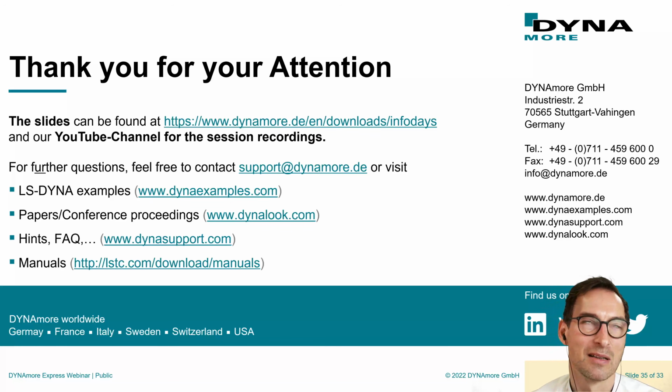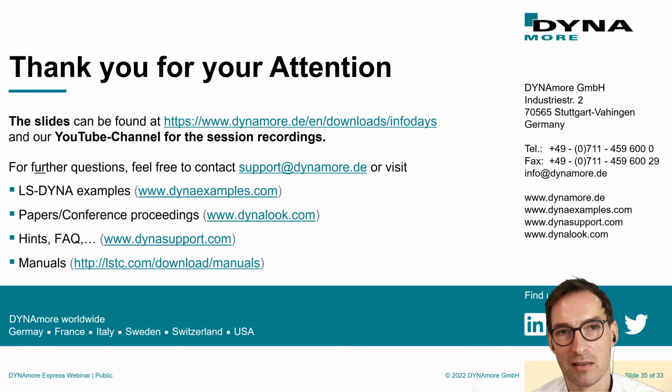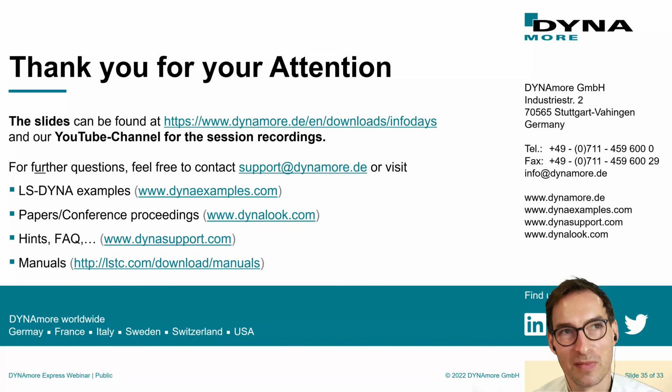I would think about how long the process is. Just keep in mind, SPH and ALE are both explicit methods, so you're constrained by the CFL stability condition. If you have a process which is slow, then I probably would give the ICFD a try. In my opinion, I would rather go with ALE than SPH, but I'm not satisfied with either of them for this particular application. These methods are not straightforward. Sometimes you have to find some workarounds.